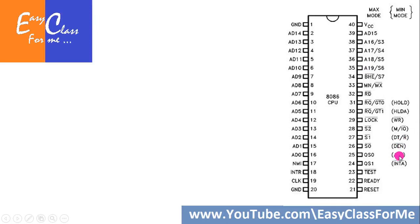When this pin is set to high in minimum mode of operation, the address from these pins will be collected into a different IC, which is a latch, and we will come to the details of that when we study the minimum mode. But just to give you a brief intro of how this functions, the address is stored somewhere in the latch.